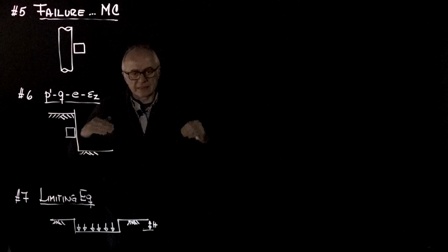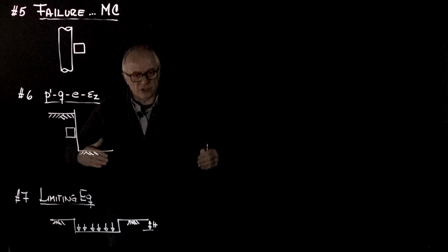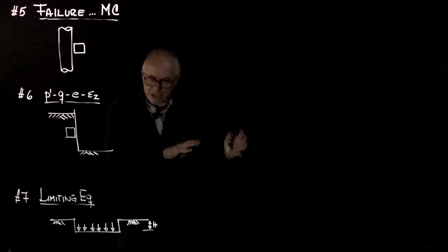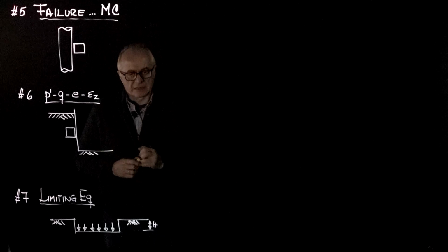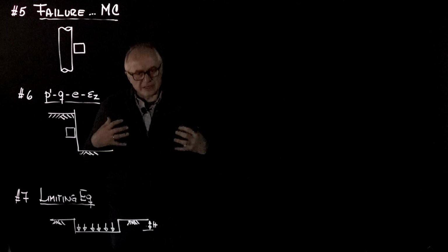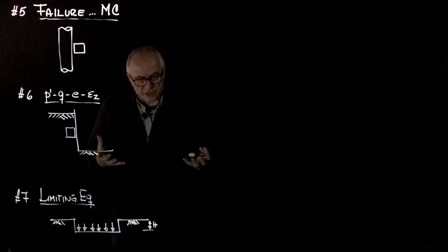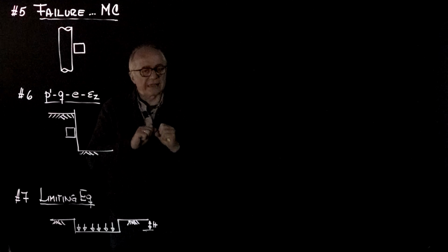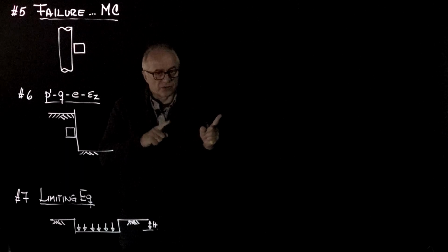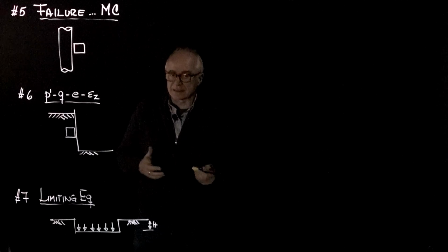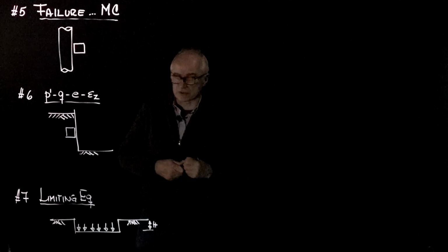So it is the additional load that the foundation or an excavation will create, a stress change, that will cause deformations. However, the initial stresses and the stress change, the combined stresses, are the ones that are going to bring the element to failure. So we cannot disregard the initial stresses when we are exploring failure conditions.